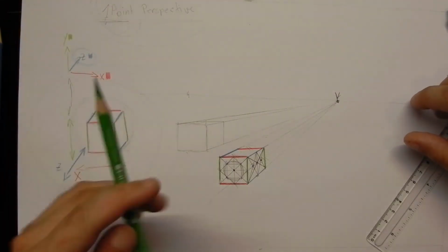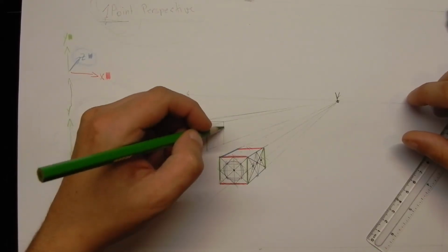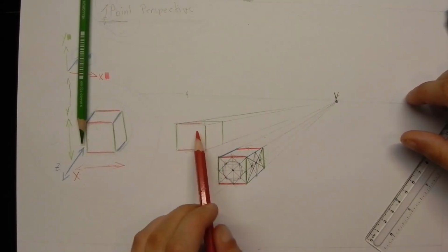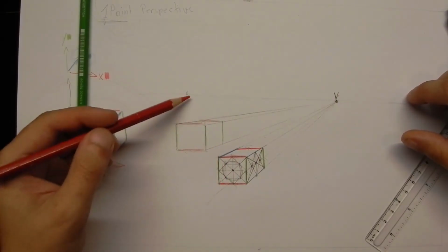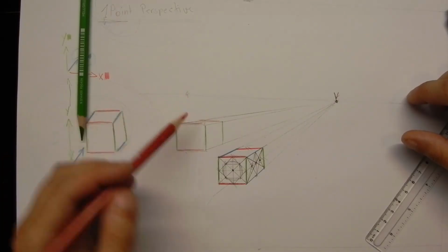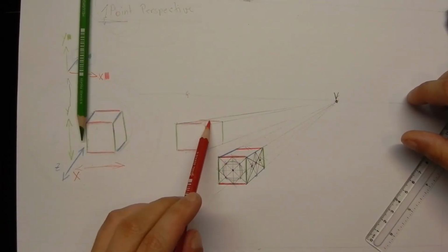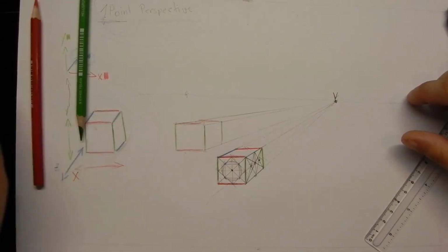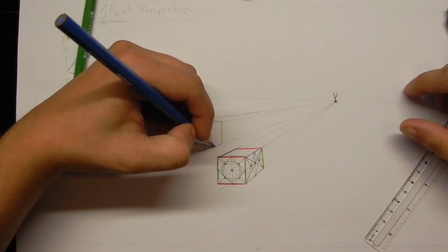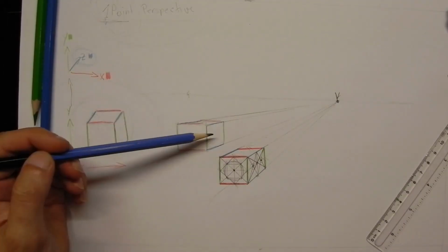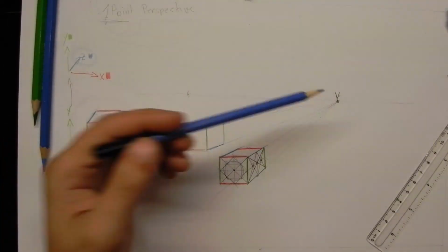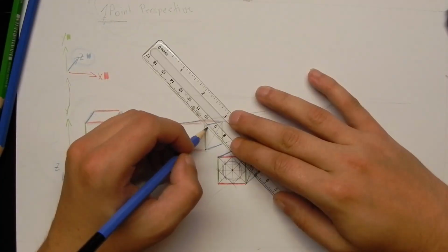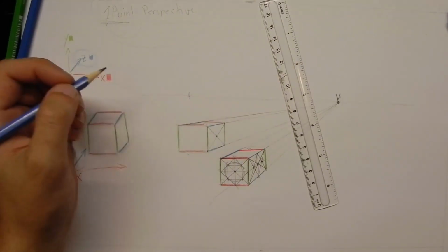As we have our second perspective cube, I draw in the Y color and the X yet again. This one is very close, since I'm closer to the horizontal line. You see the difference. This shape is actually much smaller than that one. X is done, and now our receding Z. Now we want to draw a correct circle here on this surface affected by the perspective system. Yet again, we have to find our center point. Crisscross, corner to corner, center point. Center point done.